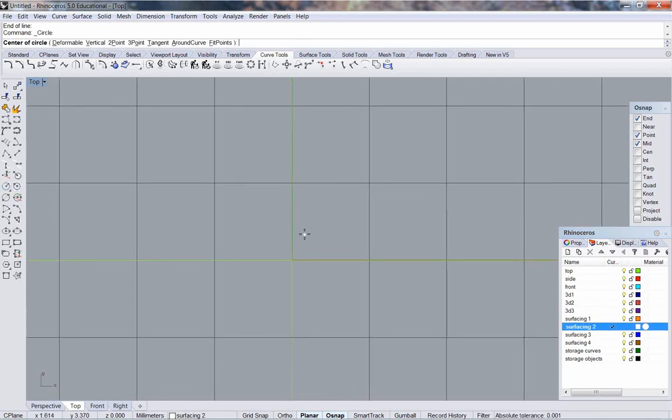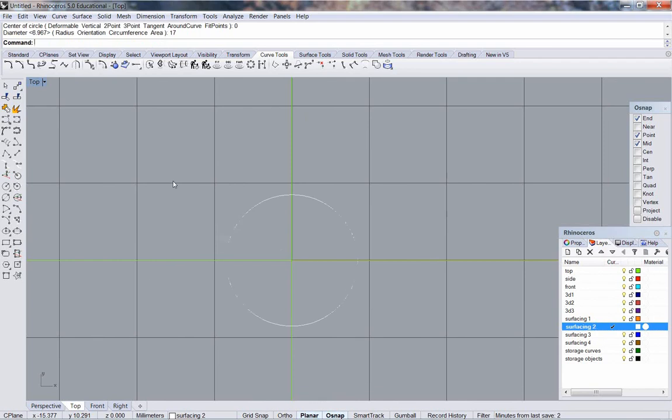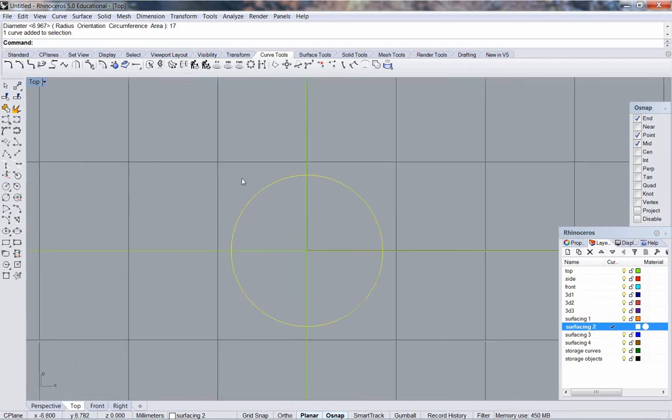with a ring bore of 17 millimeters, circle diameter, circle center radius, center of circle 0, diameter, make sure it's at the diameter and not radius, 17. Going to offset for a shank thickness of 2 millimeters. So offset 2.